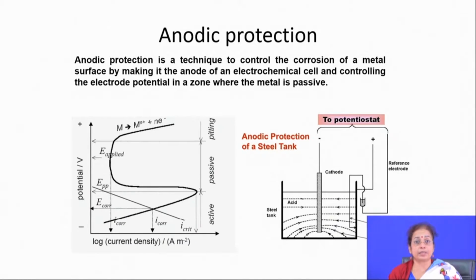So, when it increases to a large extent, naturally there is a formation of oxide scale on the surface. When there is formation of oxide scale on the surface, you will find that it is passivated, and that passive film actually helps in reducing the corrosion rate further. So, this is the case of self passivation by the anodic current. So, you will find that the component gets protected.